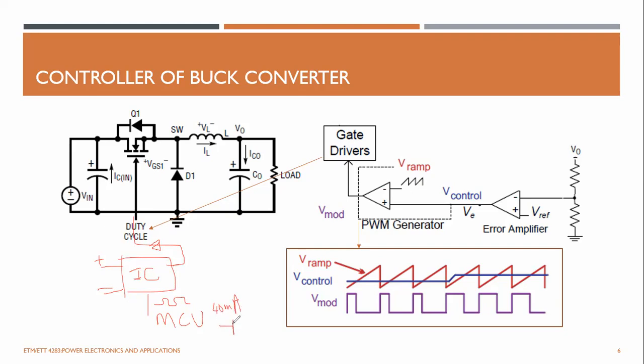You can simply run an LED. But for this kind of power switch driving, you need currents from 1 amp to 4 amps. So you provide the voltage signal coming from the Arduino, and the gate driver amplifies this to the current, driving large current pulses at the same frequency. That's why you need a gate driver to drive this one.